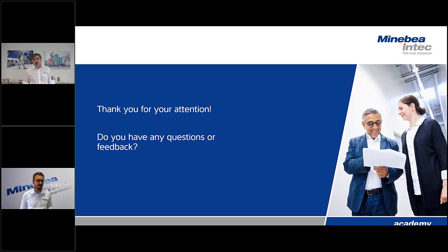And maybe you remember the one slide with the comparison where the maximum resolutions are defined referring to these accuracy classes. If you are using the load cells for a legal for trade application, it is of course very limited what you can use, given by the approval. If you are using not legal for trade, then you are quite free. But of course, the higher accuracy class is better, has better specification, and better results can be expected.